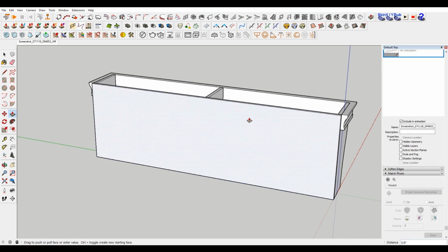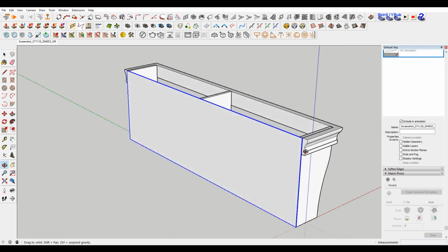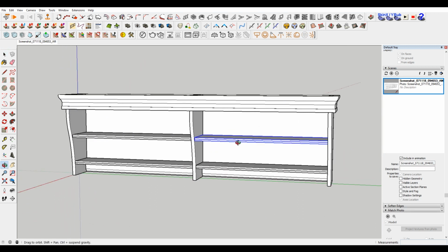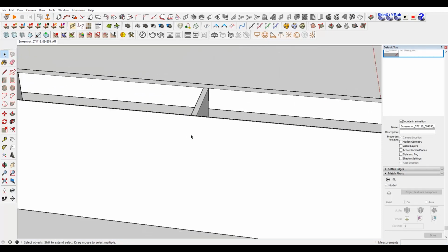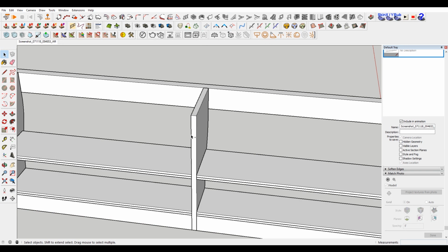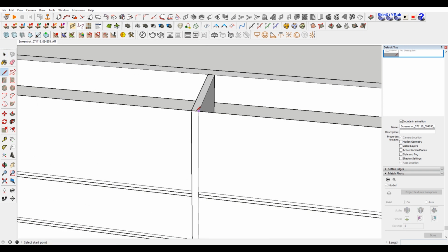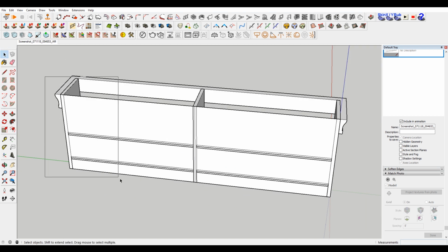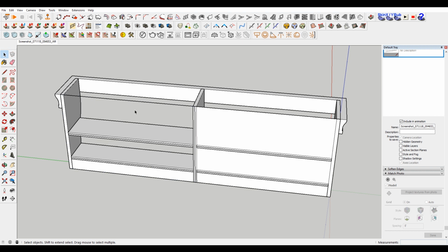Give this a little bit of a thickness, let's say 1/8 of an inch. Just group it so it doesn't become a problem later. And there we go. Actually, let me undo. It'll be easier as a 2D surface to edit this. So delete this line.